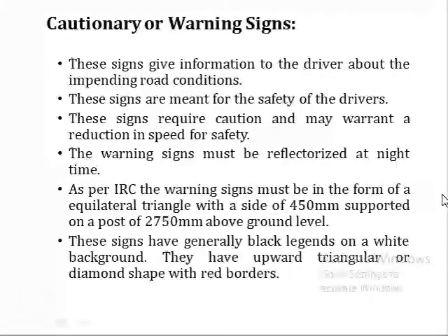First, cautionary or warning signs. These signs give information to the driver about the impending road conditions. These signs are meant for the safety of road drivers. These signs require caution and may warrant a reduction in speed for safety. The warning signs must be reflectorized at night time.